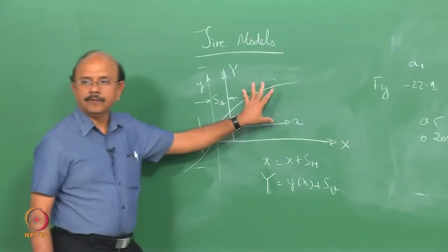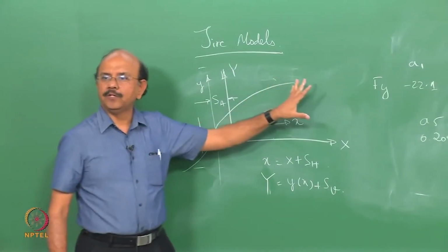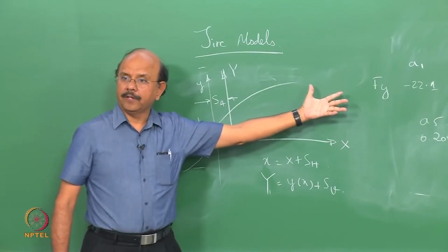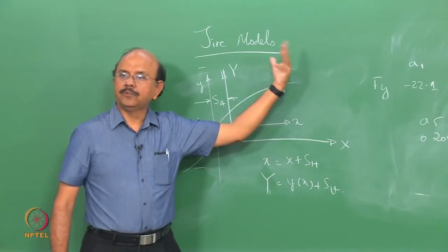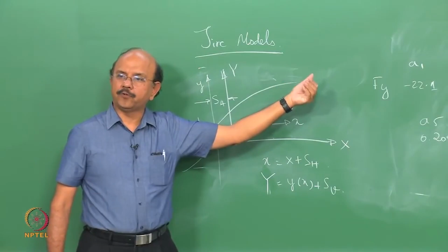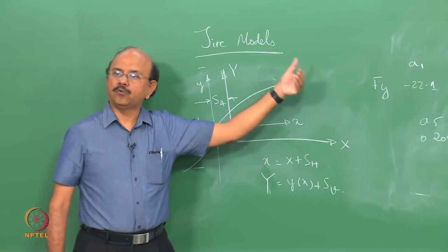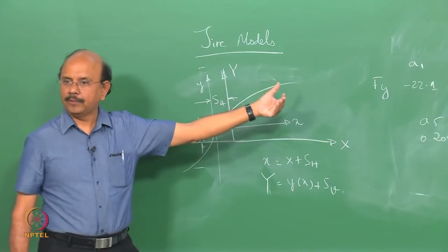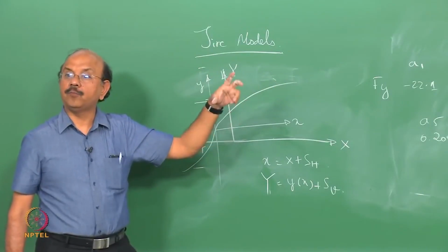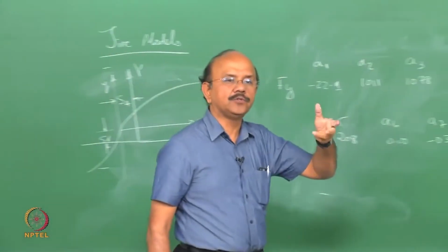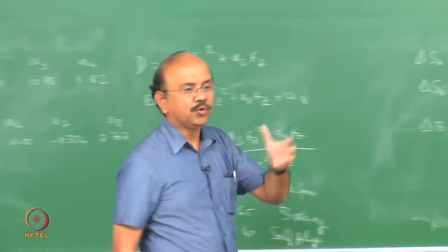What we said is that we have an experimental curve, and the experimental curve has to be input into, for example, my mathematical model of the whole vehicle, because I am interested there to determine the forces. I want to know whether my tire would develop those forces. If it develops the force, what would be the slip angle, or what would be the slip at which these forces will be developed? Where do I sit actually in that curve, and so on? And I have to meaningfully take into account the change in the FZ values, or the normal forces, that are acting due to the dynamics.